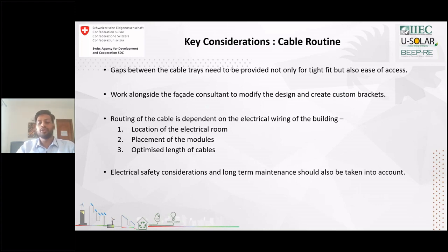This will make your project feasible, and that's how we move ahead with the design also. So most of the BIPV projects, when it comes to greenfield projects, we need to integrate the architecture accordingly for our requirements, where all the cable routes are finalized, the electrical panel rooms are planned, and the point of load injections are planned during the design stage of the building itself.